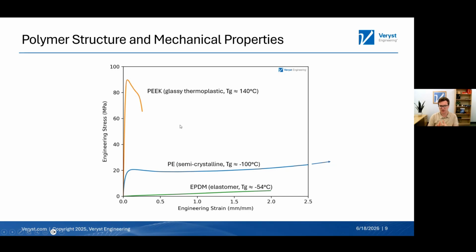So thinking about glassy versus more rubbery domains and the crystallinity of these 3 different materials, we essentially get 3 very different responses with different combinations of those properties. I like showing this type of behavior because it shows the variety of mechanical response that you expect from these different polymer materials, and links that back to whether they're glassy, semicrystalline, or rubbery.